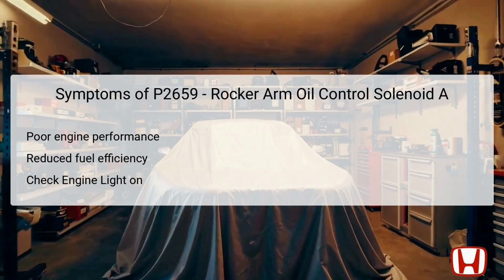Another common symptom is reduced fuel efficiency, which can occur as the engine is not operating at optimal timing due to malfunctioning rocker arm oil control. Additionally, the check engine light, CEL, will illuminate on the dashboard, notifying the driver of an underlying issue.